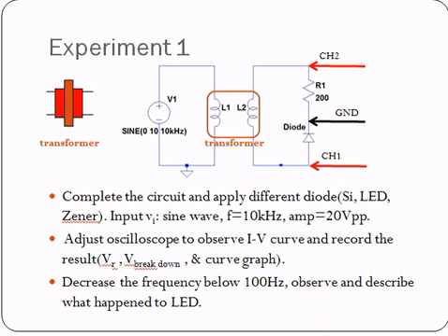We can easily derive from the equation I equals V divided by R that when R is a constant, the voltage is proportional to the current. It is clear that the voltage across the resistor represents the current through the whole circuit. Therefore, we could treat it as the current and draw the IV curve using channel 2.